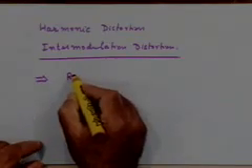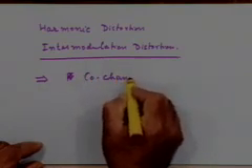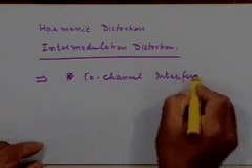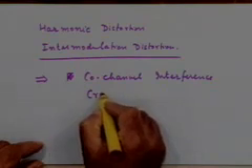Your received signal contains components outside the band. If your receiver was now trying to look for a signal in that frequency band, it will not only see that, but will also see some components from this, and this will cause a kind of crosstalk, right? It's also called co-channel interference, or sometimes also simply called crosstalk.